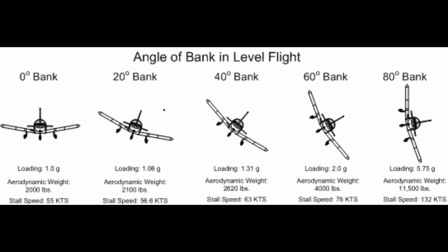Although the Code of Federal Regulations, CFR, requires the aircraft structure be capable of supporting 1 1/2 times these limit load factors without failure, it is accepted that parts of the aircraft may bend or twist under these loads and that some structural damage may occur. This 1.5 load limit factor is called the factor of safety and provides, to some extent, for loads higher than those expected under normal and reasonable operation. This strength reserve is not something that pilots should willfully abuse, rather, it is there for protection when encountering unexpected conditions. The above considerations apply to all loading conditions, whether they be due to gusts, maneuvers, or landings.